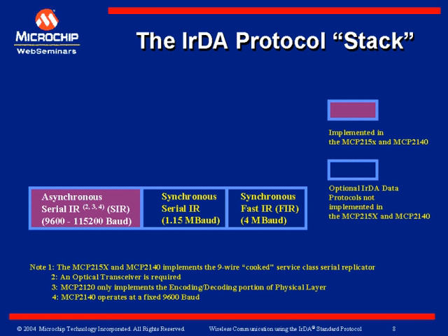Looking at the protocol stack that is implemented in the protocol handler, basically the IrDA protocol stack follows the OSI network model. But the IrDA organization has chosen to implement the structure a little different in appearance. At the bottom of the protocol stack is the physical layer. And this specifies how the data looks, basically your bit format, and how the bits are going to travel over what type of medium.